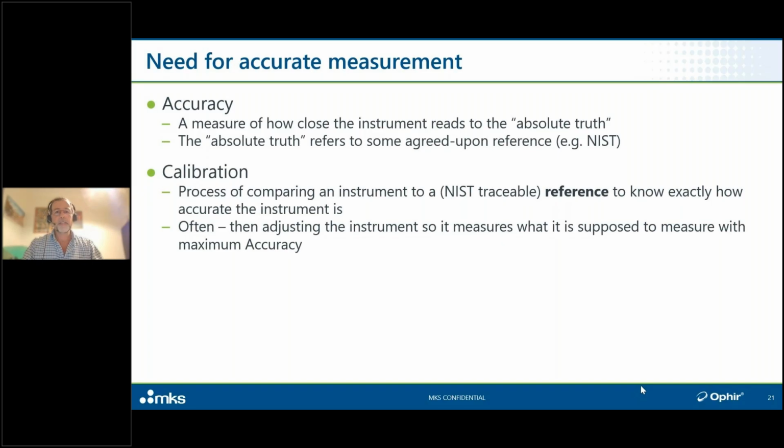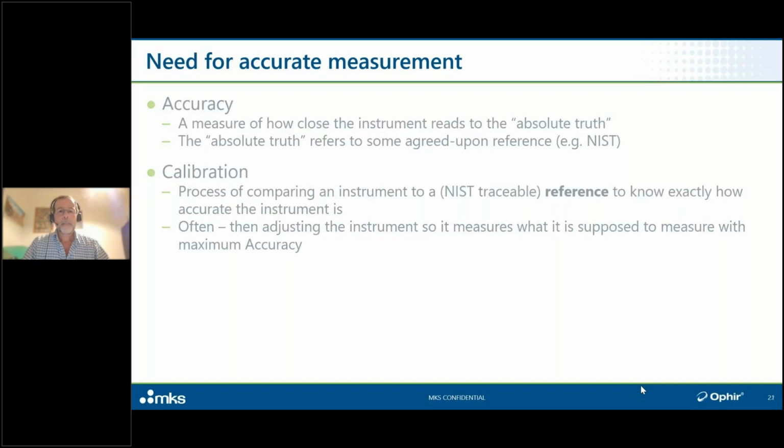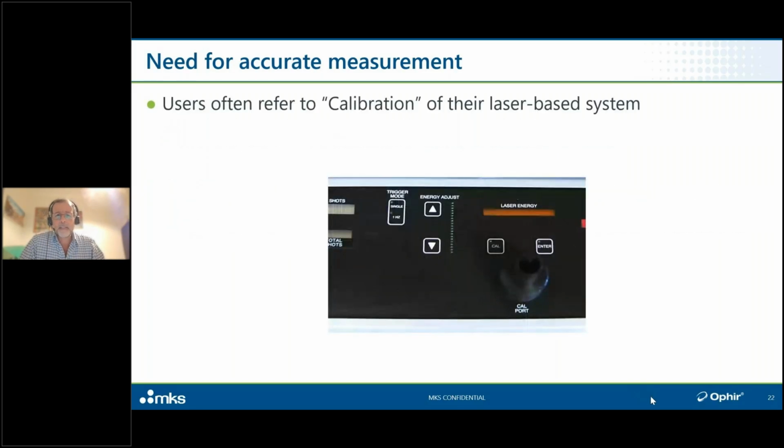So here you see just an example. This is something that we've seen in quite a few laser-based surgical systems, where what they'll often do is have a small detector inside the system looking at a tiny percentage of the power coming out of the laser, maybe a beam splitter, or in gas type lasers, there's still the rear leak, whatever it is. And they're monitoring the laser full time that way, but there are limitations to that. There's drift there. It doesn't pick up changes that happen farther downstream in the optical chain.